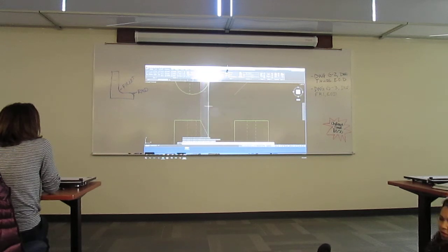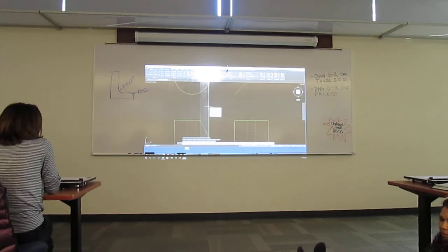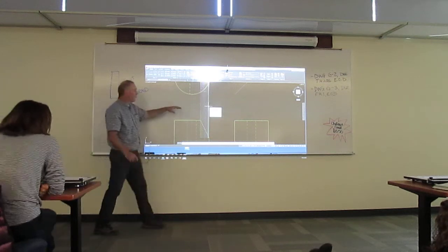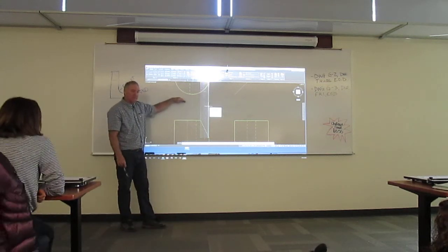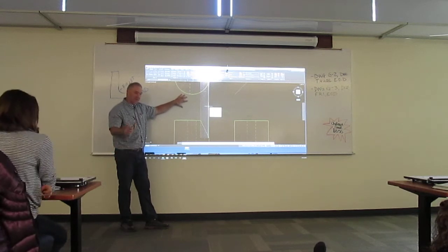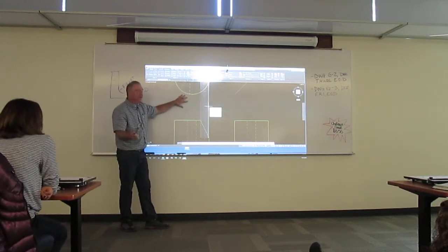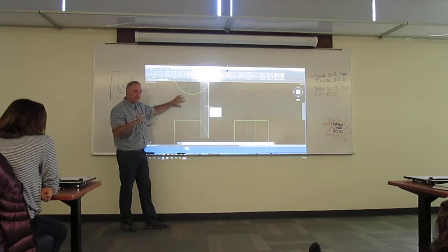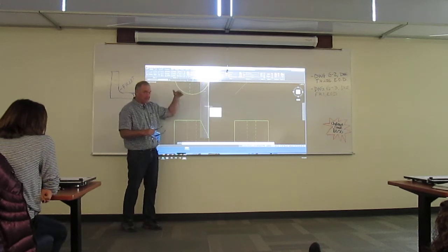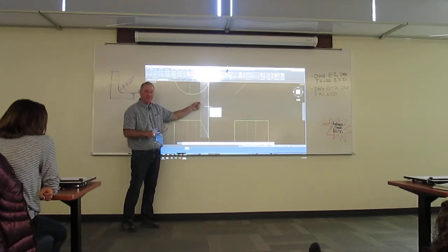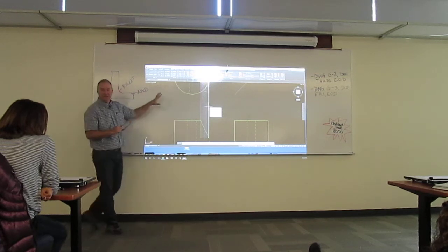If you can't figure it out the other way, this lets you break a bunch of points. The first way I did that works if you have an ellipse or a circle. And we had a cylinder we started with, so then we have to get a true ellipse. That works. If you get an irregular curve, a curve that changes radius, you have to do it this way. You cannot use the other way. This is the way we do it.